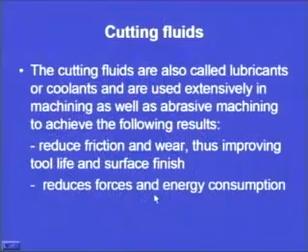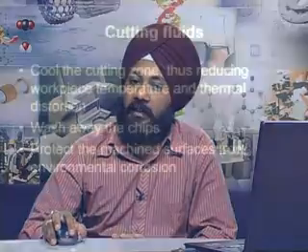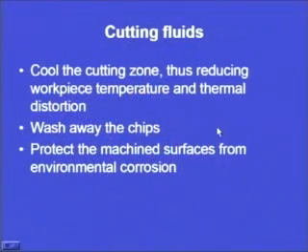It reduces the force and energy consumption. Moreover, it will cool the cutting zone. We have seen that the temperature rises to a substantial level in the cutting zone. So, it will cool the cutting zone, thus reducing the workpiece temperature and thermal distortion. Thermal distortion results in a number of deteriorating effects. So, the cutting fluid will cool the cutting zone, thus reducing the workpiece temperature and thermal distortion. So, the workpiece distortion will be affected. Then it will wash away the chips. The cutting fluid can be used to carry away the chips. Also, it protects the machined surfaces from environmental corrosion.